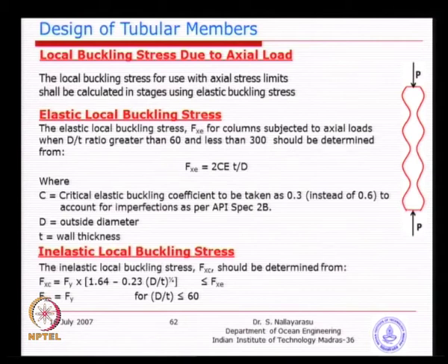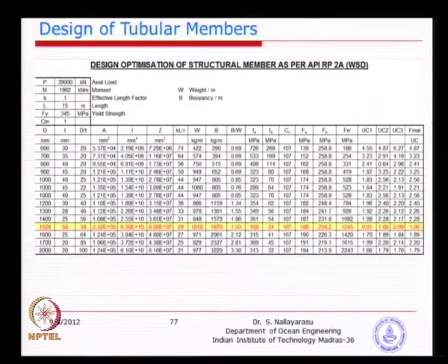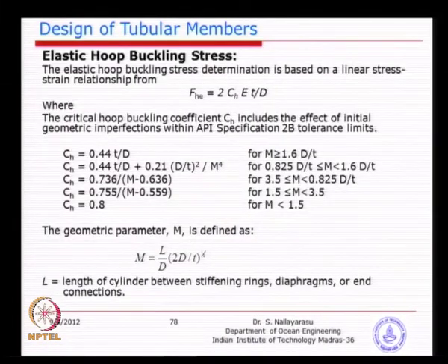As long as you provide a ring in this location, for example, a circular ring, the pipe will not be able to buckle, because the rings will hold it by taking a shear force. So, if you provide rings, you could get additional stress. In this equation, you take either the initial length or the ring spacing, from one ring to another. So, the m parameter can be controlled by introducing additional rings, not necessarily a structure to be attached to, because it is only local, not a global buckling.